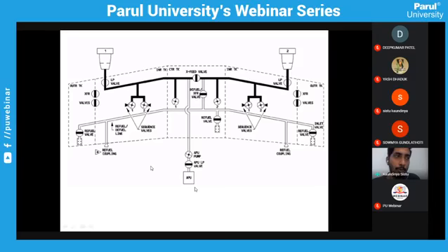Fuel should be injected through the fuel nozzles with a certain pressure. Unless you have a certain pressure, it won't get distributed properly. So even if you get fuel here without turning on the APU pump, you will have problems. The valve should be open and the APU pump should be on to get fuel into the APU. Okay, if I close this valve as well, then it will go, but the booster pump is a dead end.